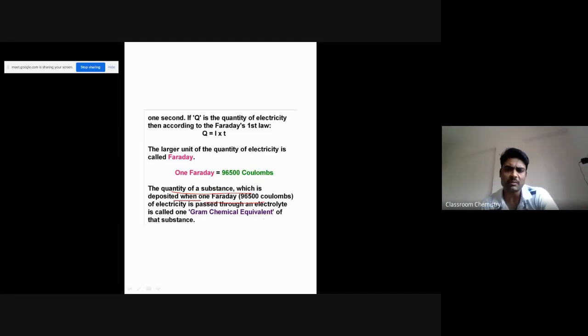Here we see different types of electrolyte. If I want to electroplate copper, then I select an electrolytic solution like copper sulfate. If you want to electroplate a particular cathodic rod with gold, then you take a gold solution or any ionic solution containing gold. You have a choice to select different types of elemental or ionic solutions as electrolyte.